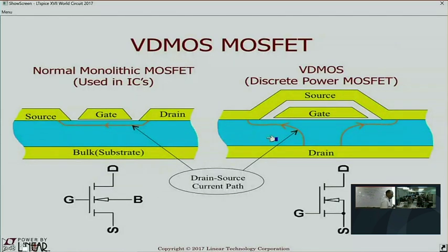Now that channel is rearranged in order to fit that transistor, in order to fit that channel on a die. The electrodes are rearranged. They look like this. This gate is an array of islands of polysilicon. It's an archipelago of the gate polysilicon. Okay, the channel is this region here. This is channel region, and that is channel region. So the width, and then there's many of these polysilicon gates over the whole die. So the width of this transistor would be the perimeter of one island times the number of islands, and that could be 10 meters even on a fairly small structure.